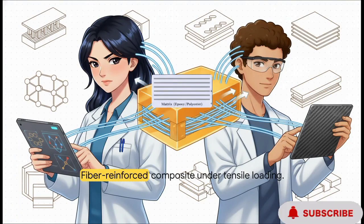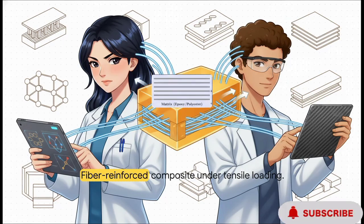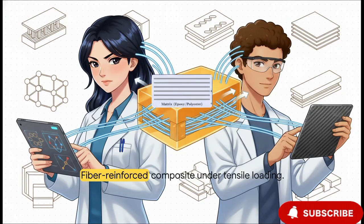Let's think about how this physically works. In a fiber-reinforced composite, you generally have two distinct parts playing together. First, you have a continuous block called the matrix, often something like an epoxy polymer. The matrix's entire job is to bind and protect the second part, which are the fibers suspended inside of it. These fibers are the actual muscle. They are what carry all the heavy physical loads when the material is being pulled or stressed.